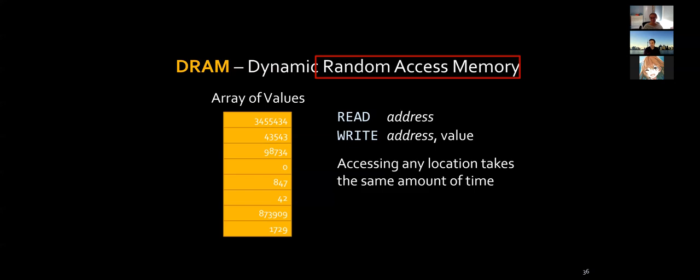It's a hassle for the programmer, it's a hassle for the designer, because if I'm going to build a chip where cache can generate different latency within the same layer, I need to buffer this somehow. I cannot expect whether it's going to take 4 cycles or 6 cycles, right? So dealing with random latencies is very painful, right? Usually you need to provision for the worst case. Okay. Does it answer your question, Terry?